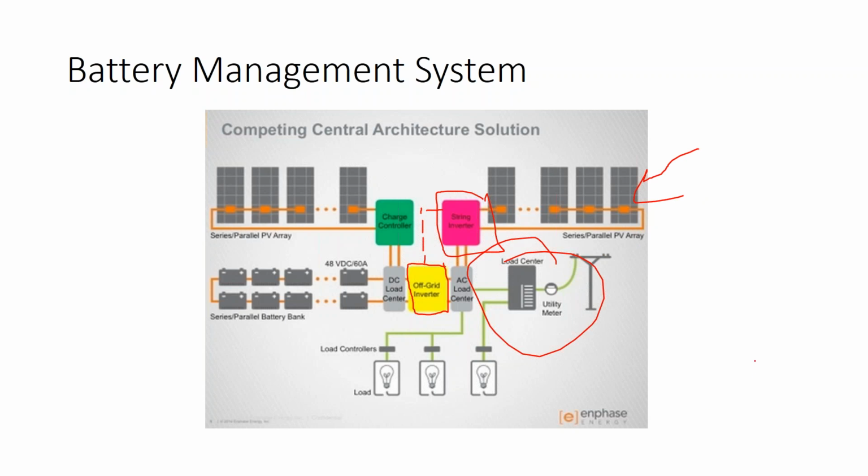If they're not the same manufacturer and you don't have that communication, the way that the battery inverter protects the system is the same safety provision that the grid uses to protect its system from the solar array, and that is the battery inverter will fake a power outage.